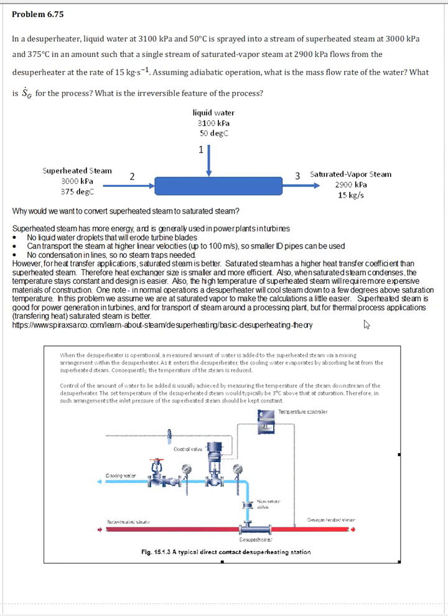Another reason why you wouldn't want to use superheated steam in big thermal process equipment is that when the temperature is higher, the construction of materials is usually going to be a lot higher, and we're talking about more complex equipment, not just pipes that are used to transport steam from one place to the next, but heat exchangers, which have lots of pipes, twists and bends and turns and baffles and valves and everything else that's involved in a heat exchanger.